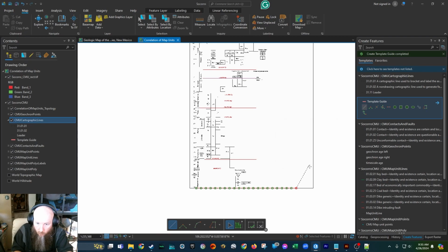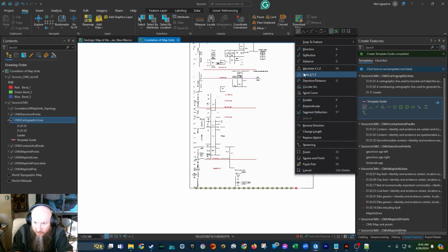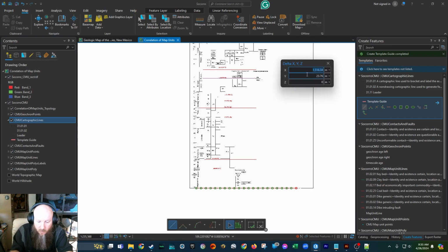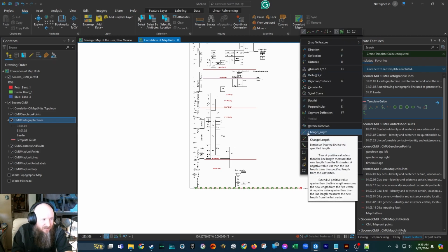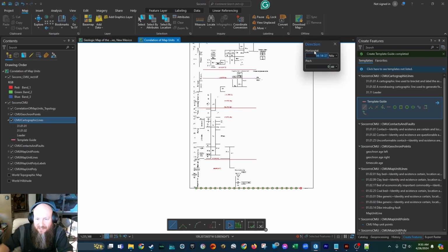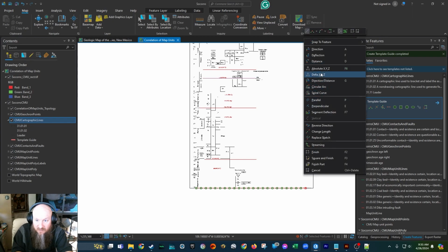If you wanted, you could create what's called a fishnet, and I don't know if that's what it's called in Arc Pro, but there's the fishnet tool that would build you a grid of boxes in the X and Y axis that are spaced out. You could make them 1/2 inch by 1/2 inch boxes by typing in those dimensions. But I wanted to keep this simpler because that tool is not the easiest tool to use. It becomes much easier when you've used it a couple times, and I wanted to keep this in the simplest terms so that it was easily understood what I was physically doing.